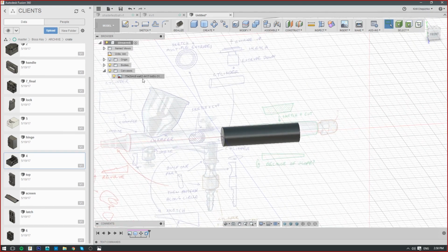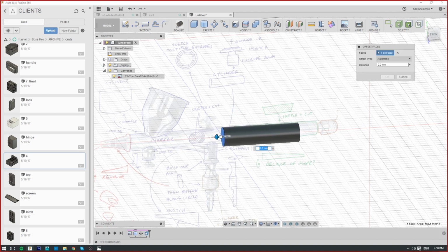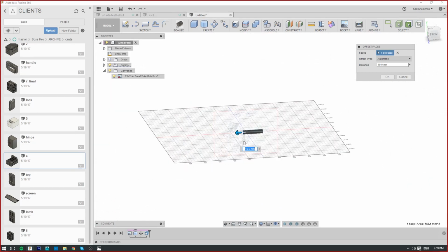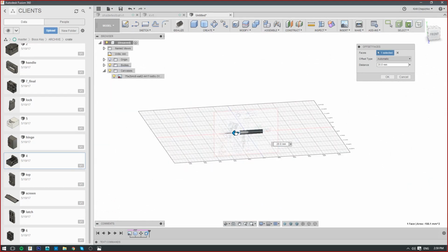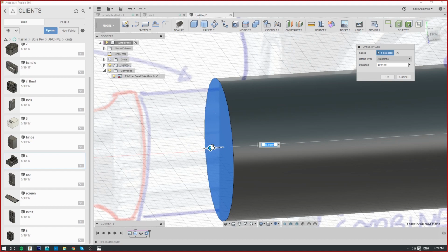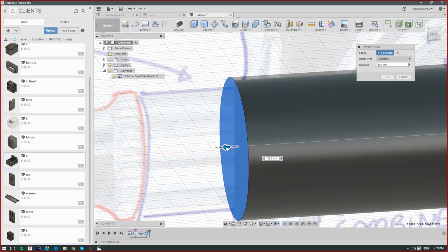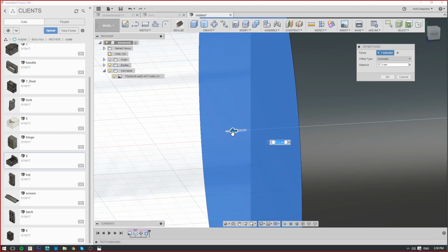I usually just move it around and press pull like this, because the one trick that not everybody understands is the amount of the stepping that happens in the digits really depends on your level of zoom. If you zoom out, the stepping will be in tens of millimeters, like 10 millimeters more, 10 more, 10 more. But if you zoom in, your stepping is now half a millimeter. It's like working with jewelry and having a magnifying glass. The more you zoom in, the more detail you will get out of it.